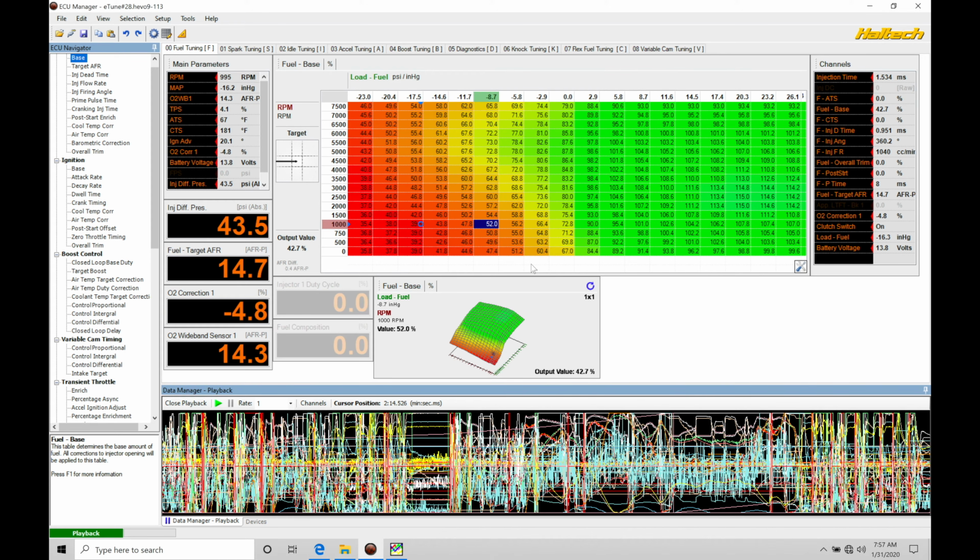Now, in our training course, we've covered the concept of working with the open loop and closed loop style calibration methods within our main VE table. In the open loop method, we're going to compare what the actual wideband is reading to what our target air fuel table is doing, and we're going to be moving up or down our main VE values so that we represent our air mass properly so that our air fuel is going to be right in line to our target.